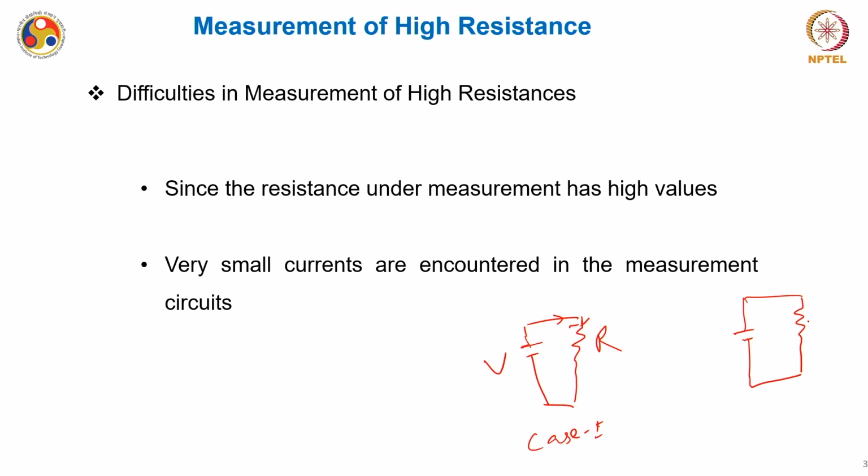Of course, we have to see it in a broader perspective, where we might use an ammeter-voltmeter methodology or any other method for medium resistance measurement, but I am giving you a simpler view. This is case 2, where the same battery is connected. However, this resistance is now 10 power 6 R, and this is current I1 in case 1 and I2 in the second case.